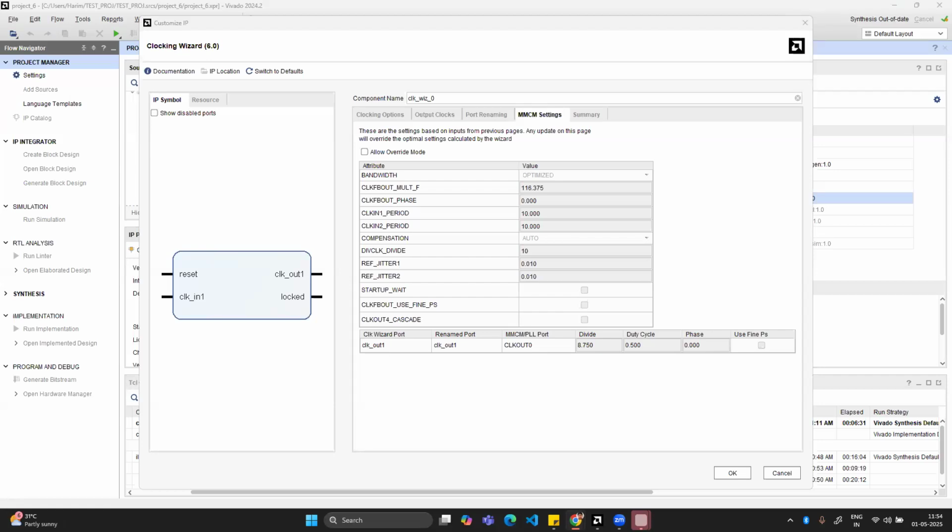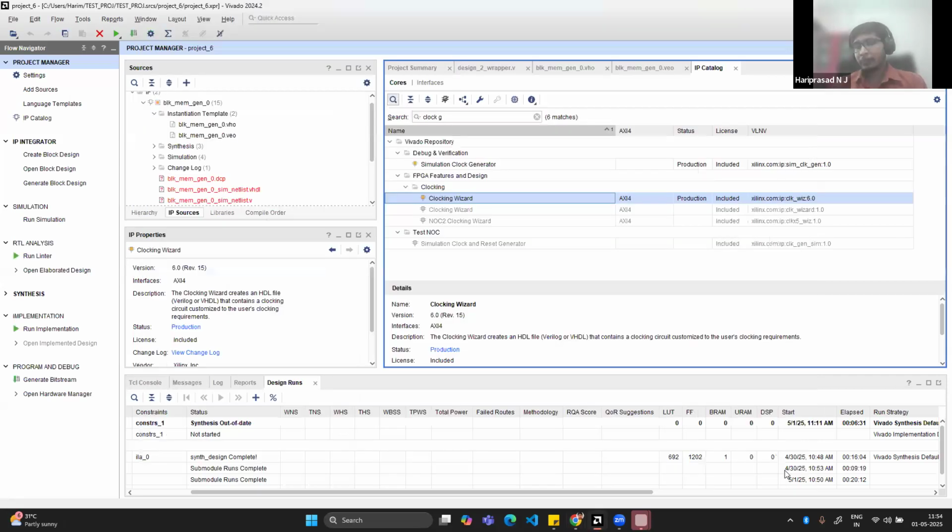A few hints on debugging. With respect to debugging, as we discussed in yesterday's session, mainly we have to use ILA, the integrated logic analyzer. In Altera-based FPGAs, we have signal tags, and if you want to debug high-speed devices, we have something called IBERT, where you can see the eye diagram, you can see bit error, you can see Eb/N0.